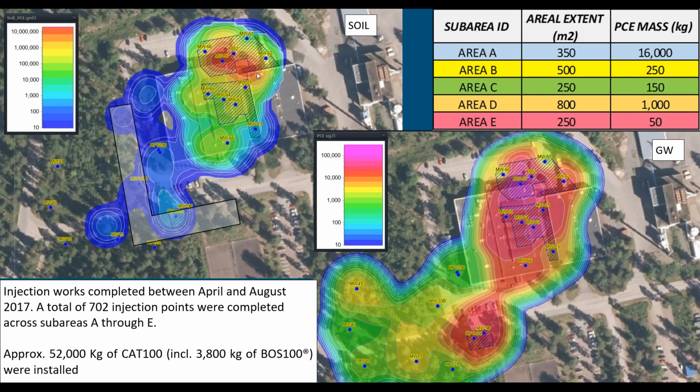Once the RDC was completed, though, and we realized how concentrated the soil mass was, we revised the approach and discussed with the client the opportunity to target the source much more actively and, let's say, cut the head of the snake and then work indirectly on the plume.